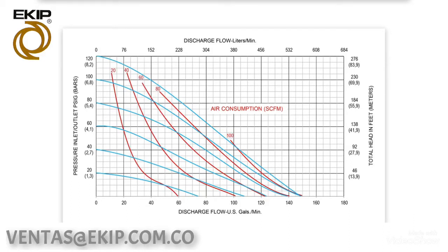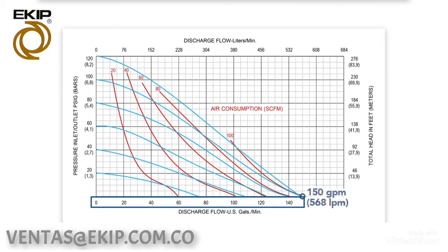The operating range is the minimum to maximum gallons or liters pumped per minute. This is identified by quickly looking at the horizontal axis data range as well as considering the air inlet blue curved axis. For example, this performance curve is defining this AODD pump's overall operating range from a minimum of 0 gallons per minute to a maximum of over 150 gallons per minute.